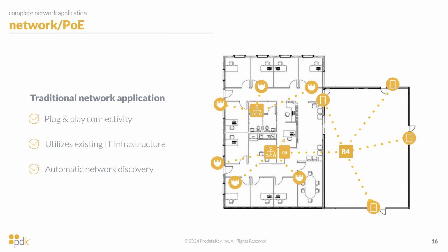So this shows you a typical Ethernet setup, or a PoE setup. You can see here we have a cloud node installed somewhat centrally next to a switch because the cloud node itself always has to be plugged into Ethernet. So the cloud node's plugged into that switch, and then that same switch is plugged into several door controllers.